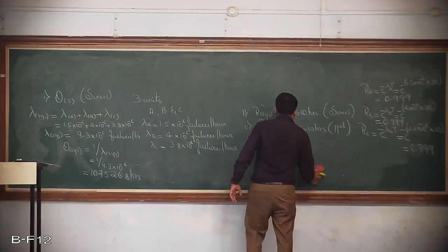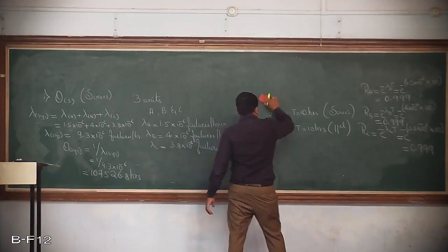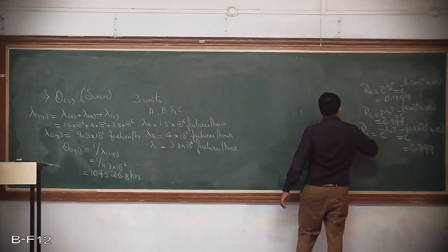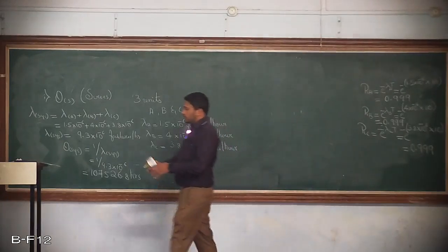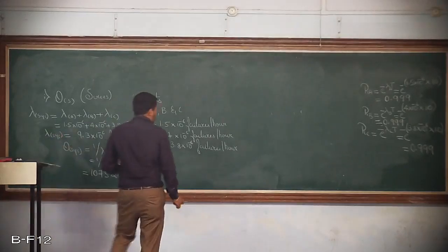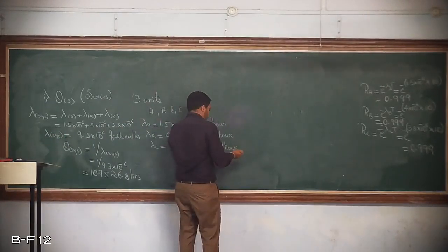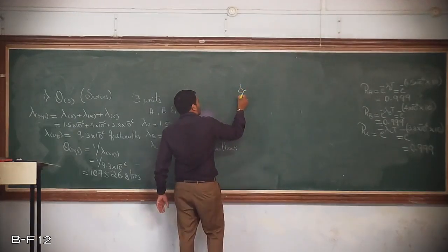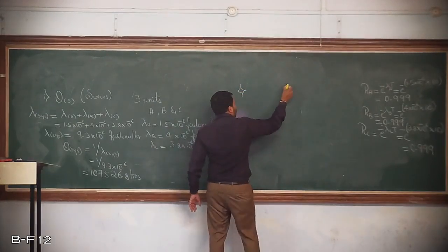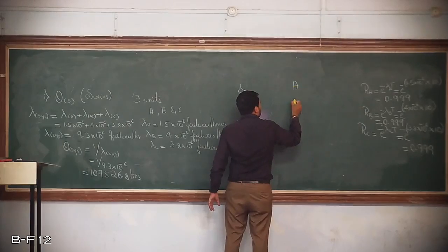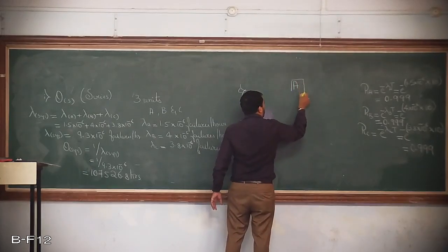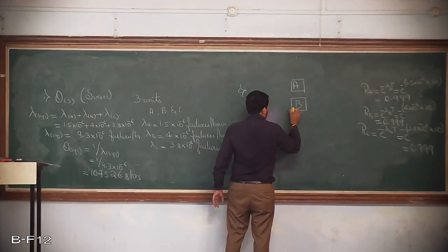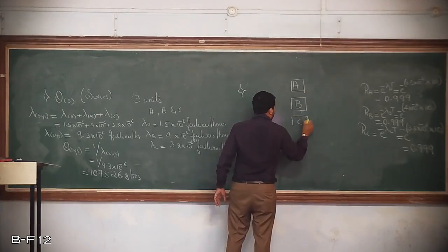Now we'll consider C. We need to find out the reliability of the system when the parts are connected in series. So assuming these three parts are connected with part A and part B in parallel, and part C in series.